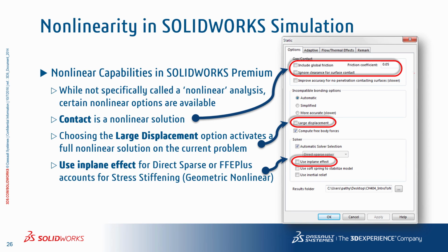If the in-plane effects are considered in the analysis, the stiffness of the structure will be a function of loads as well as deflections, which themselves are functions of loads. So using this in conjunction with the large displacement option will probably make more sense to calculate the contributions of the in-plane effect to the overall geometric stiffness. But keep in mind that as a user, we have no control on how the nonlinear solution progresses and completes in a linear static situation like this.